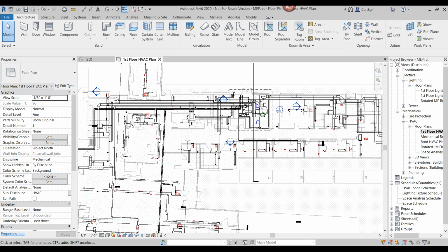Now, maybe a more powerful demonstration of this would have been to use it in a schedule, because with light switches, we want them 4 foot from the floor. The duplex receptacle, I want 18 inches from the floor, that sort of thing. But I just wanted to caution you with that a little bit, because what we'll do commonly in family editing is to make the insertion point 4 foot below the switch.